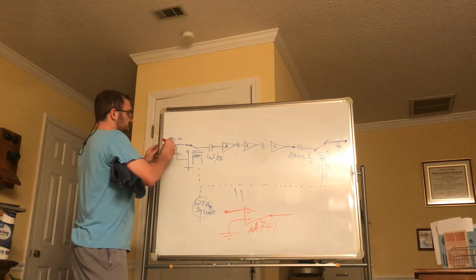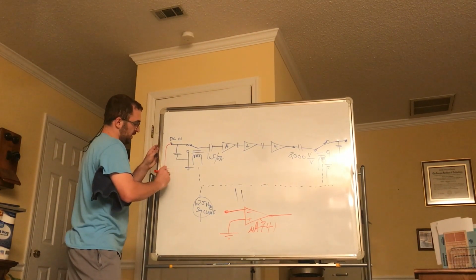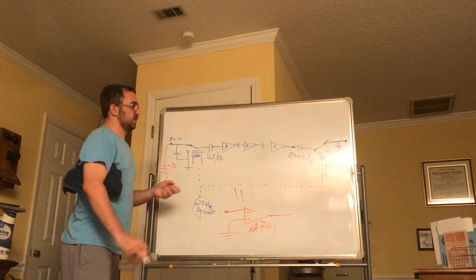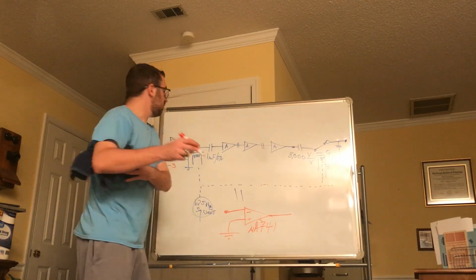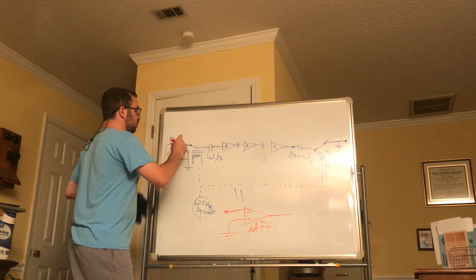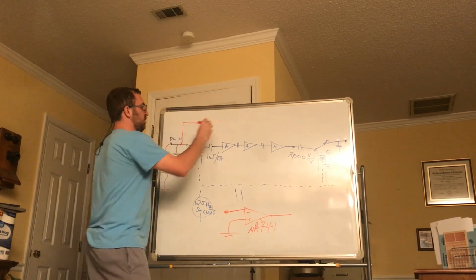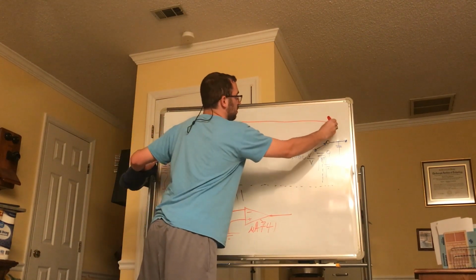So if you put any little signal here, and it would be negative, or you might use positive. Say you have a -3 volts. That's going to try to give -24,000. You can't do that. Well, we can use negative feedback. And what you would do is you would hook up your feedback resistor from the output of the DC side to the input.